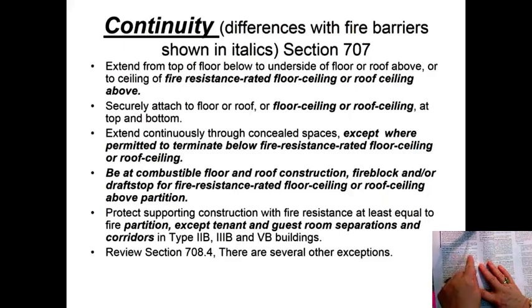So 2 hours or more where connecting 4 stories or more, and not less than 1 hour where connecting less than 4 stories. The number of stories connected by the shaft enclosure shall include any basements, but not any mezzanines. A mezzanine is if we have one particular floor, like the first floor, and then you have a balcony or part of a floor that comes out. Shaft enclosure shall have a fire resistant rating not less than the floor assembly penetrated, but not to exceed 2 hours. Shaft enclosure shall meet the requirements of this section.